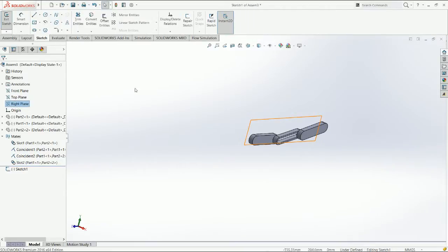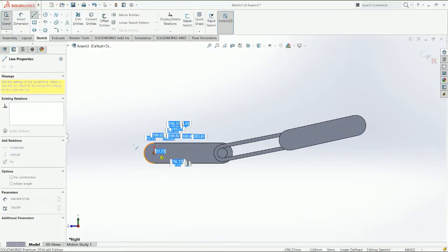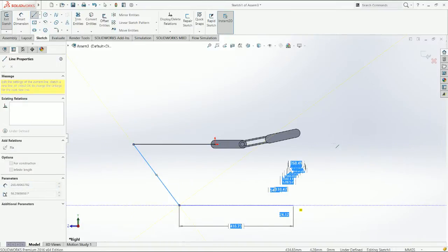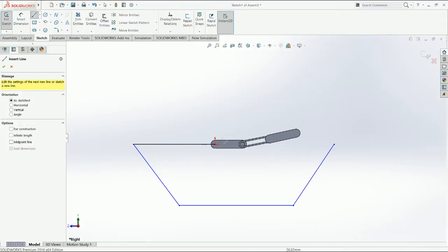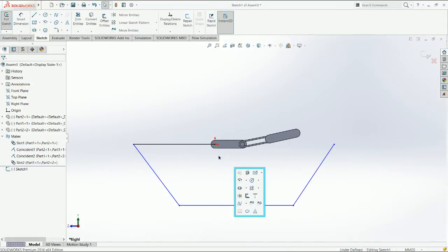I'm gonna create a sketch, and I'm gonna create it like this. Just gonna make this shape. And now I have two options. I can close it with another line, but that's gonna be two different segments, or I can use extend entities, which is below trim entities, and that's gonna extend it up to the next point.